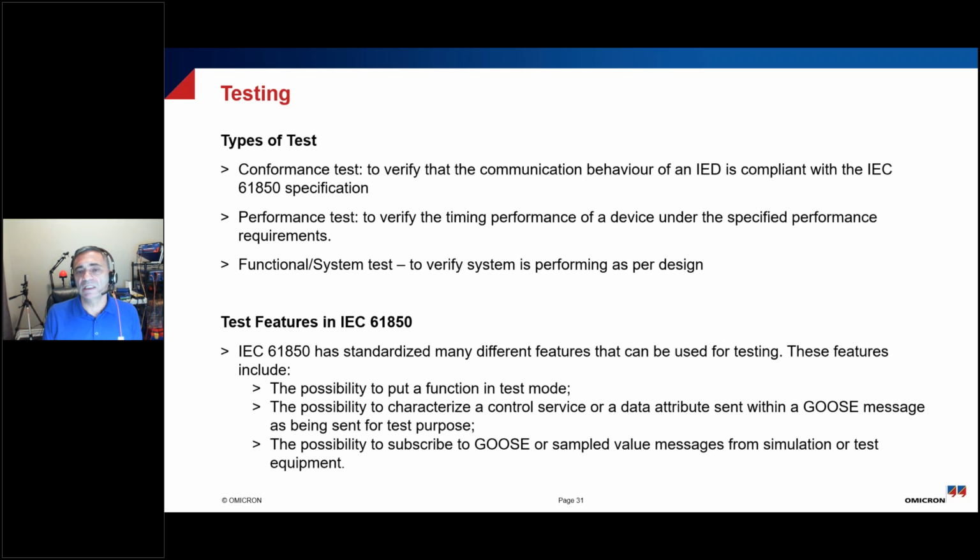The testing is conformance testing that the individual relays actually comply to the standard and that they meet the performance requirements. And when you've designed a system, that the system functions the way it's supposed to, the way you designed it. And then there are test features within IEC 61850 to test the relays while they're in the system.